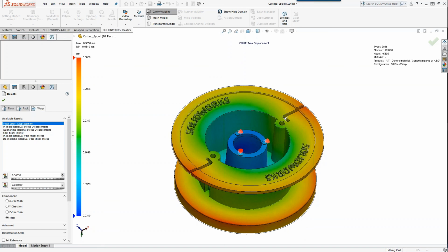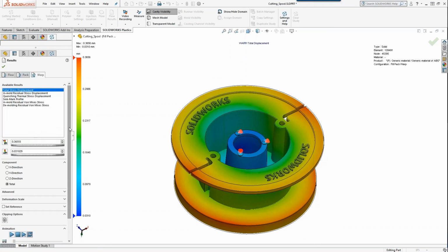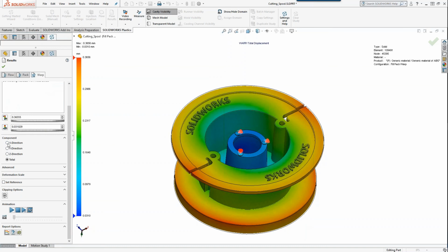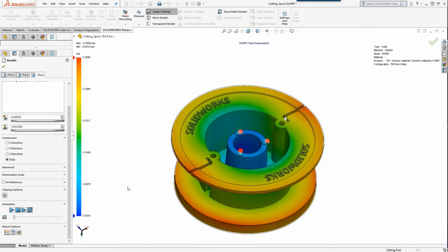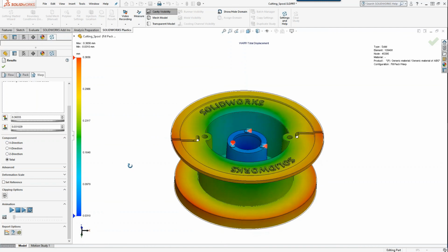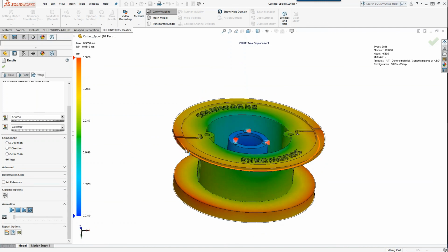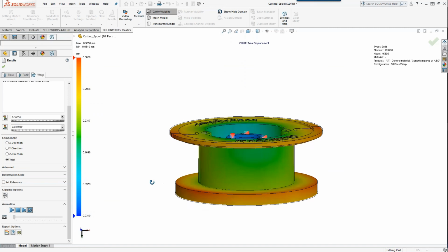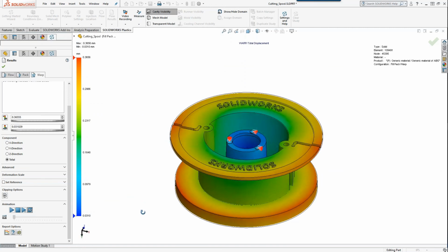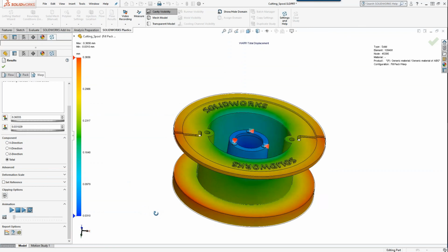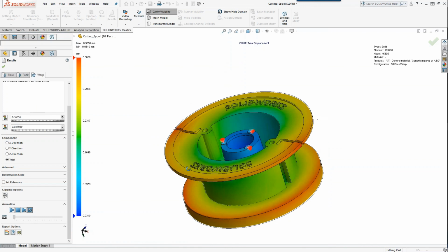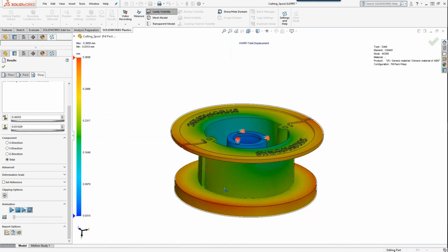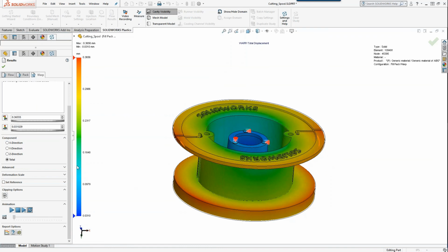So here you can see total stress displacement, and we can identify the displacement in the X direction, Y direction, and Z direction, and of course total. So the color here correlates with how much that part is displacing, right? And based on this, it kind of looks like we have maybe a taco shape. Well, not so much, because this is in two directions. Taco would be all four. But we can start to see how this part is displacing.